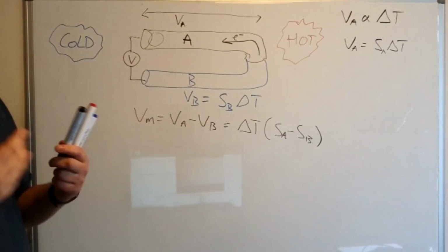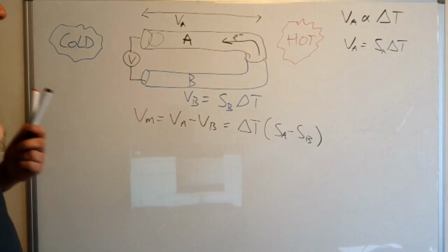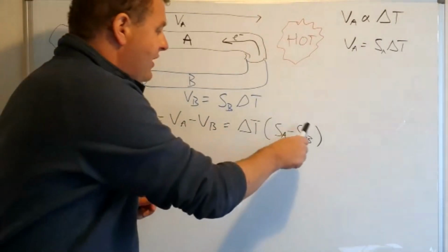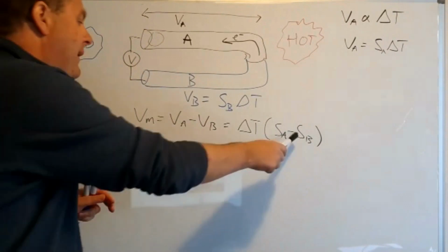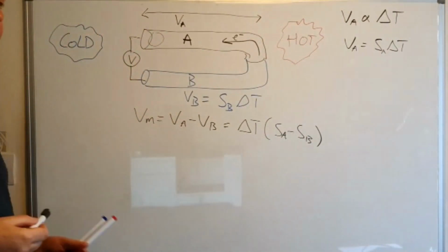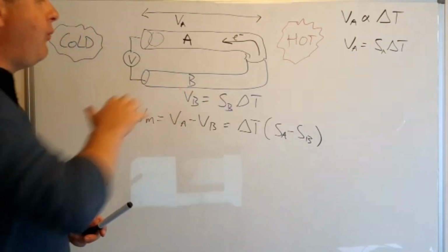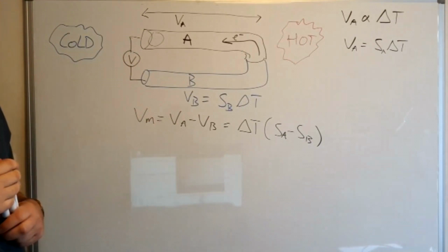And likewise, again, if you're trying to measure at cryogenic temperatures, you would pick different thermocouples. The problem is that as you get colder and colder and colder, the Seebeck coefficients both tend to go down to 0. And as a result of that, the difference between them gets smaller, and so the thermocouples get less sensitive. So again, understanding the background physics of why your sensors work helps you to pick a sensor that is good for the type of thing you're trying to work with.